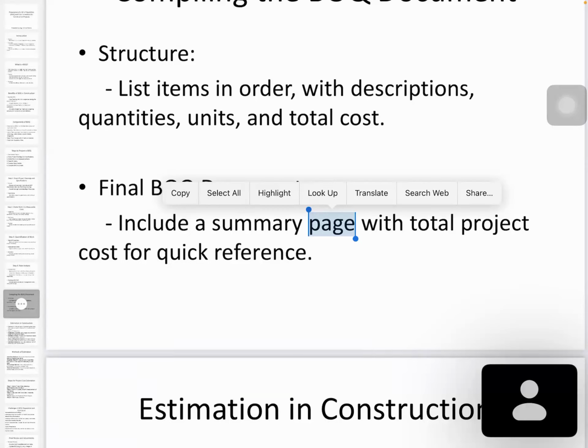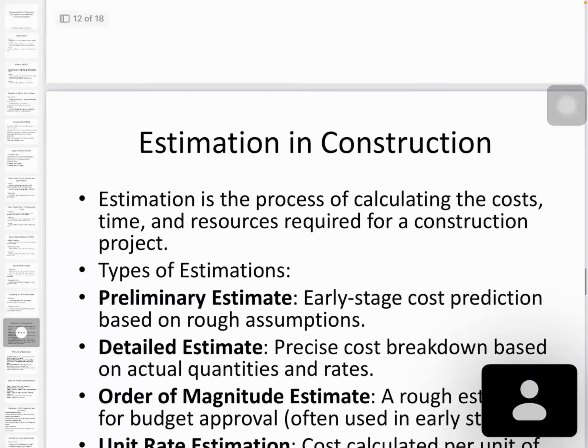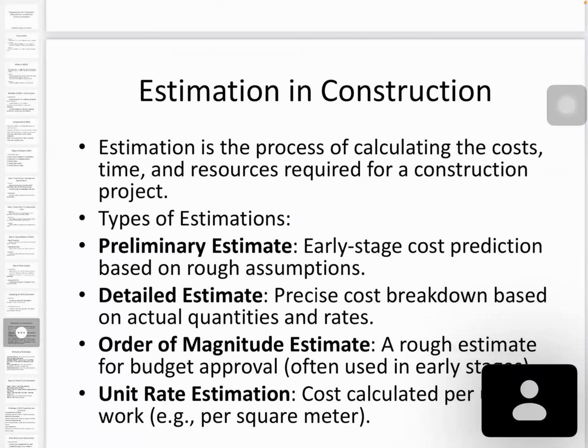Based on the engineering estimate, you have to go for different grade-rated contractors for the bid. At that time you need the budgeted BOQ to determine the engineering estimate, and normally we float our BOQs without the rates. That way we can get competitive bidding by preparing a proper BOQ.